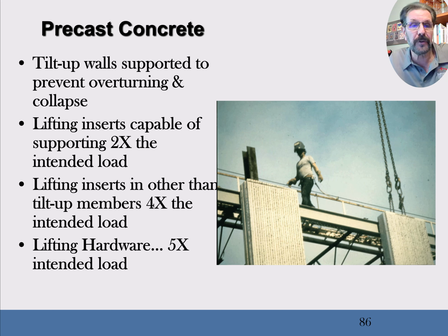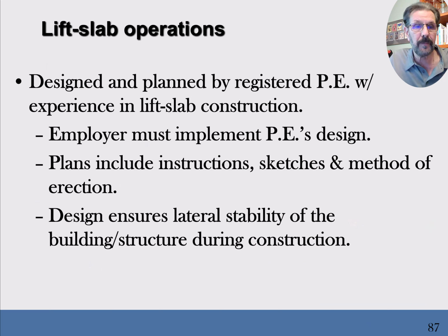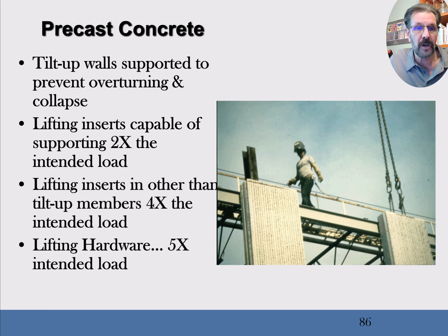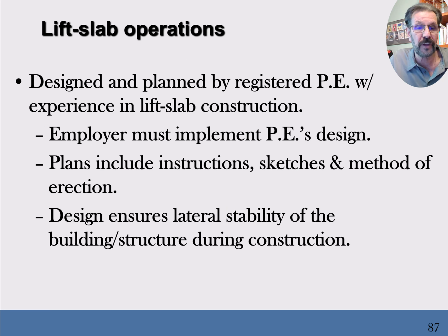So when we're talking about tilt-up panels, sometimes people will call them lift slabs, but really most people in the industry do not call the tilt-up wall panels lift slabs. The lift slabs are horizontal slabs. And so in lift slab operations, what they do is they pour all the concrete slabs one on top of the other, and then they jack them up afterwards.